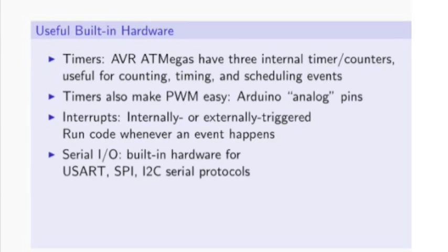There's a ton of built-in serial peripherals. We talked about these earlier. There's asynchronous serial, SPI, which is good for really fast communications to a small number of devices, and I2C, which is a little slower, but it's kind of got a network flavor to it, so you can address 128 different devices off of that. And all three of these run independently and on their own.